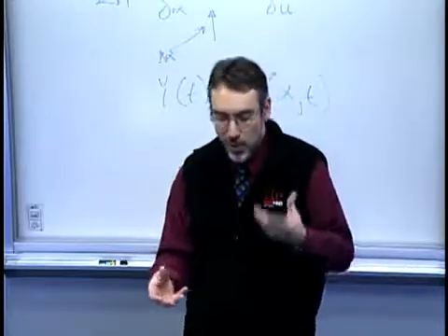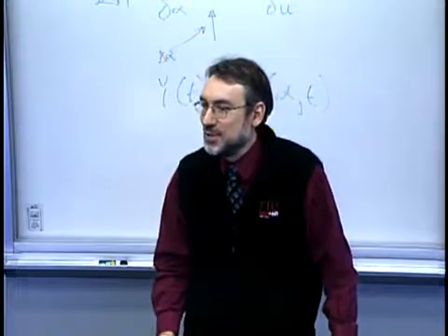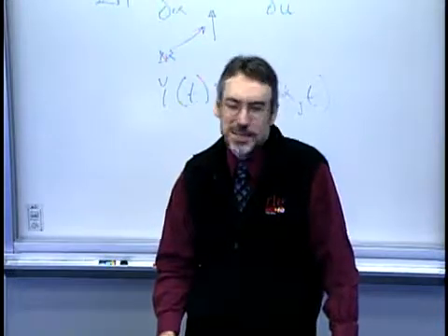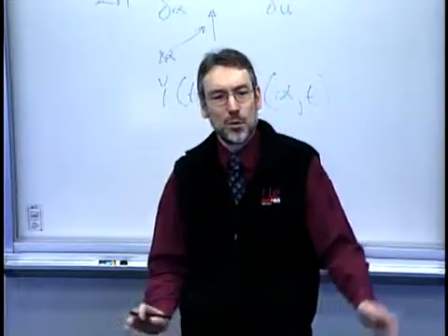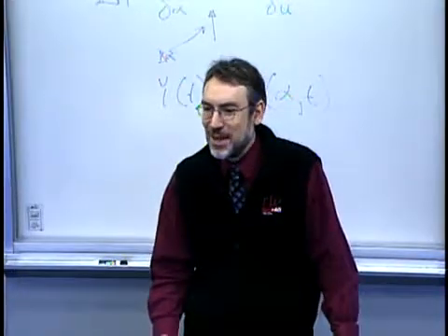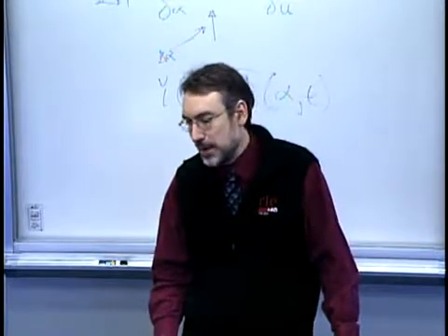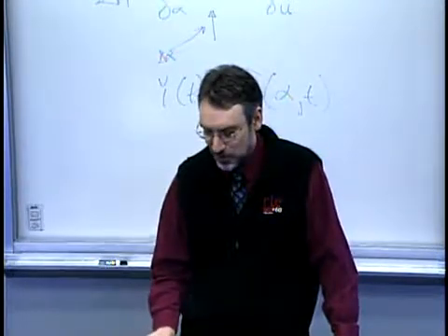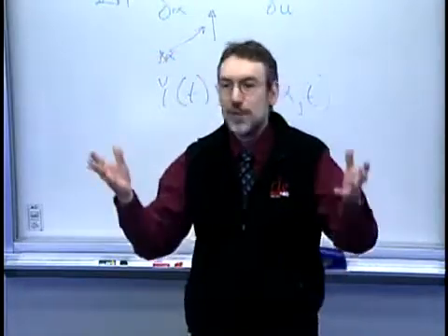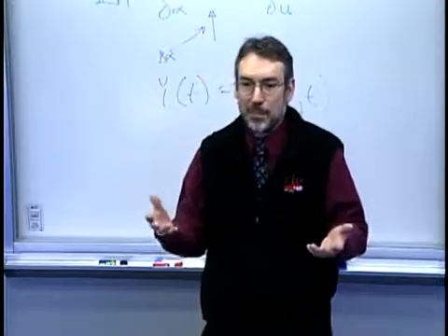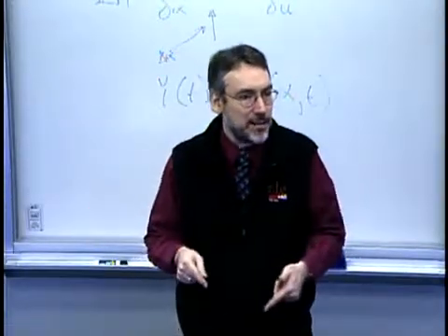So it's not always an indication that there's part deviations. In some sense, the measurement equipment is a manufacturing process tool or equipment itself that is also subject to deviations. And in fact, part of the applications of some of the statistical methods we'll talk about seek to characterize or do gauge studies of the accuracy and capability of your measurement equipment and the components of variation that affect that.